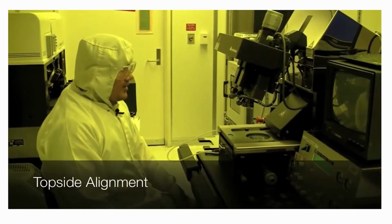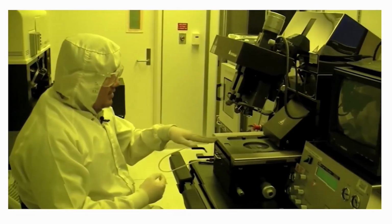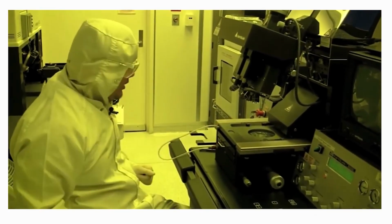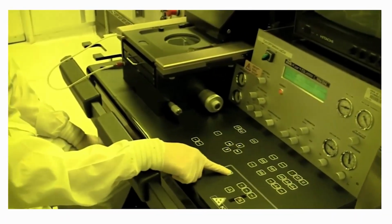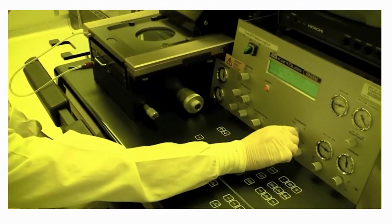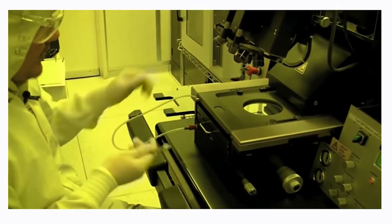What we're going to do now is topside alignment, by using the microscope on the top to align to the wafer that's underneath through the glass. So to do topside alignment, we need to remove the backside microscope. So we press this button, that turns it off. Also, we need to put the illumination to the top side. And then we can load our wafer in.